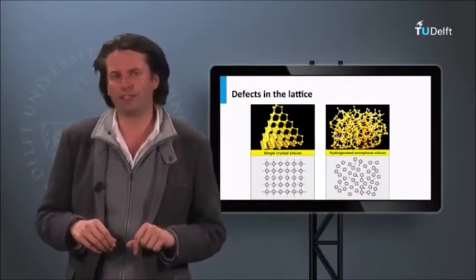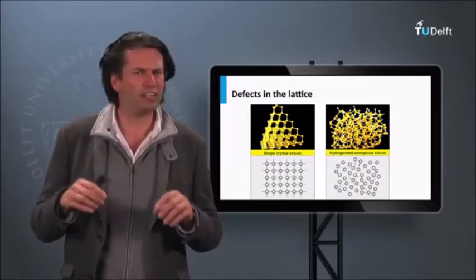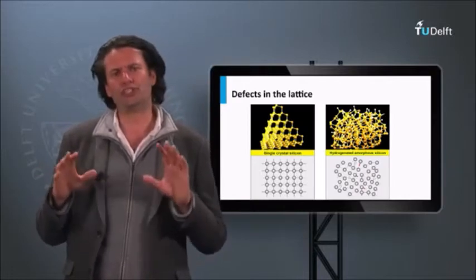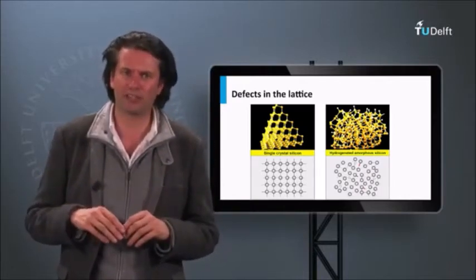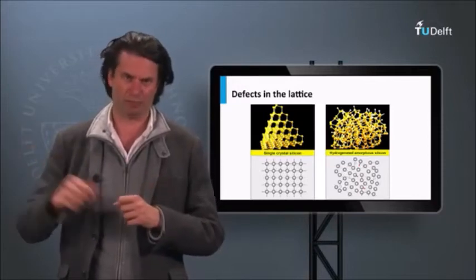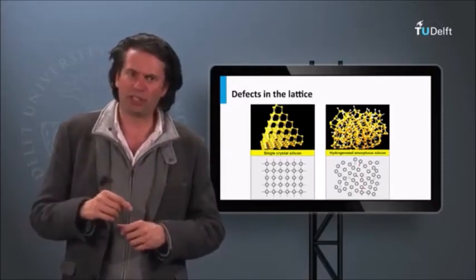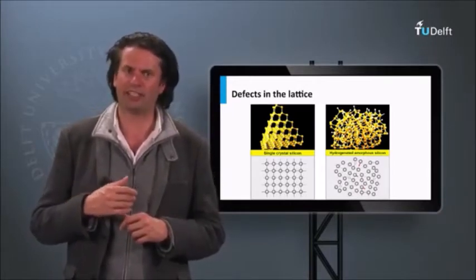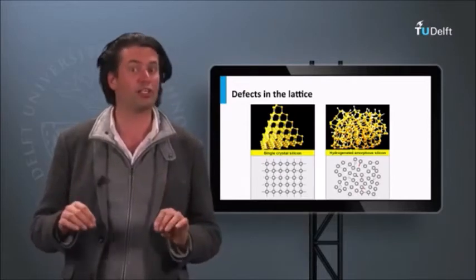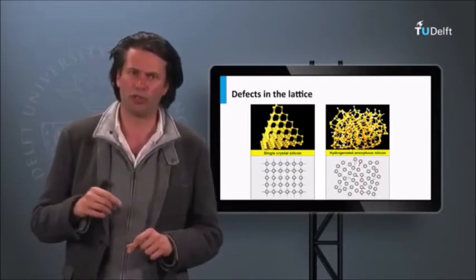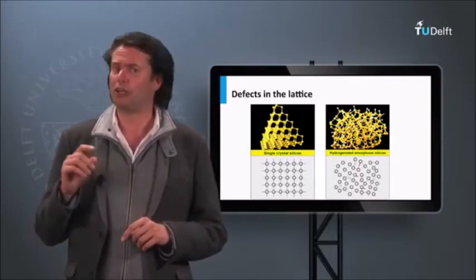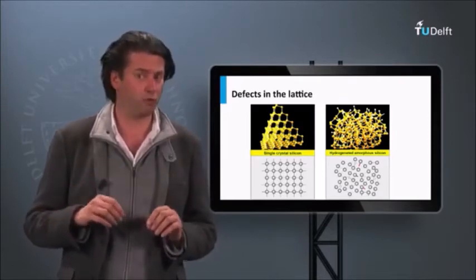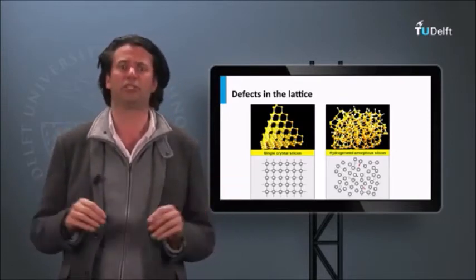The hydrogenated amorphous and nanocrystalline silicon films have a relatively high defect density in reference to crystalline silicon. Due to the disordered structure, not all valence electrons are able to make bonds with the neighboring atoms. The so-called dangling bonds can act as defects. This means that the lifetime of the light-excited charge carriers is limited by the Shockley-Read-Hall recombination, which controls the diffusion length. The recombination is so high that the diffusion length of the charge carriers in hydrogenated amorphous silicon is only 100 up to 300 nanometers.